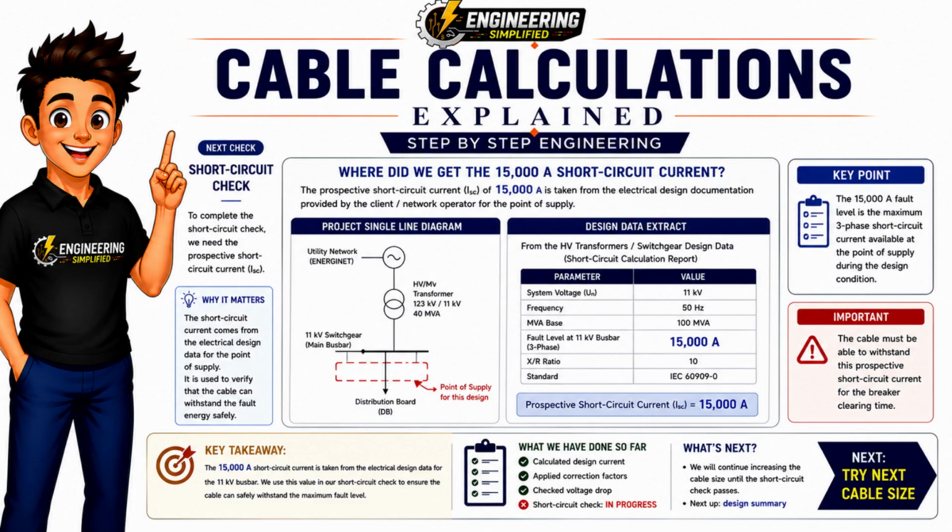This value is not guessed, and it doesn't come from the cable manufacturer. It comes from the electrical design documentation or fault level study for the installation. The fault level depends on the supply transformer, the electrical network impedance, and the location of the equipment within the system. For this example, the calculated prospective short-circuit current at the 11 kilovolt switchboard is 15,000 amps.